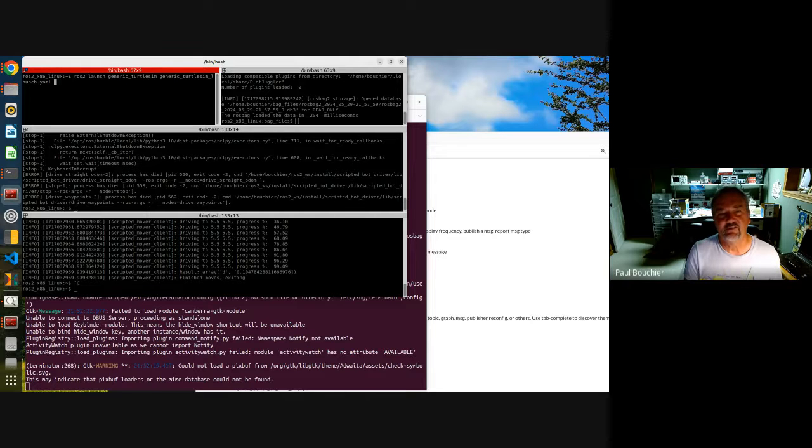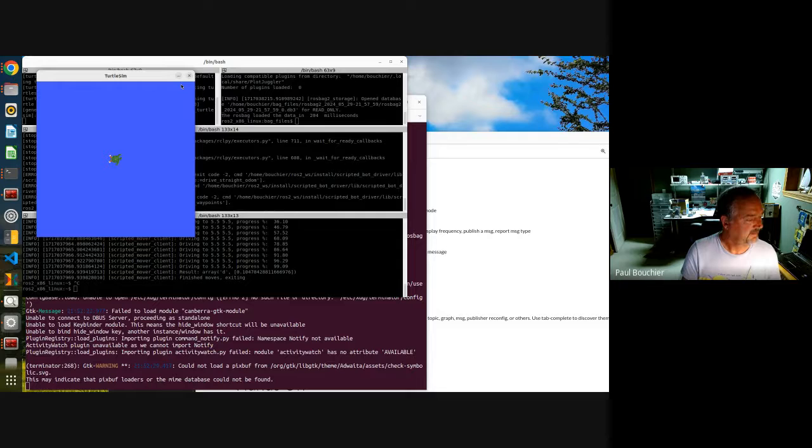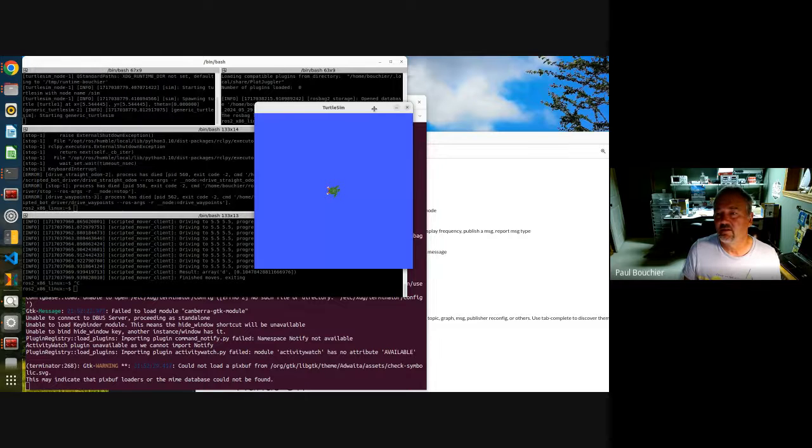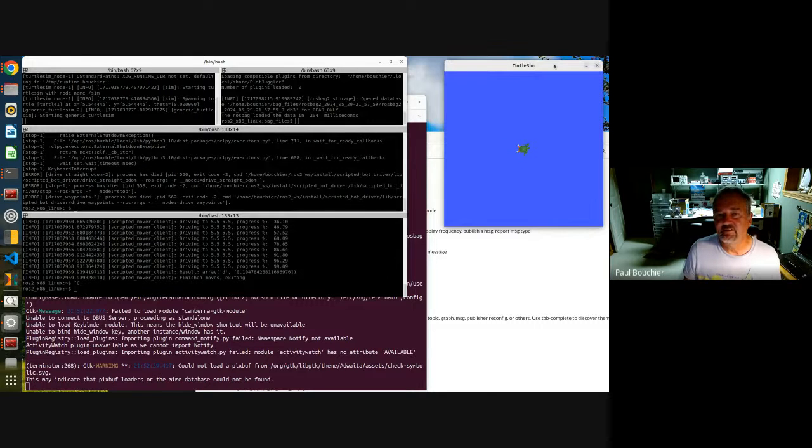This is based on TurtleSim, but gives it a generic interface in the sense of it monitors cmd_vel for motion commands and emits its pose as an odometry message on the /odom topic. And so the TurtleSim simulator has started. The turtle is at 5.5, 5.5 in the middle.